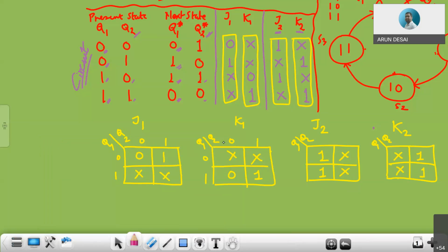So in this case, 1 is there, so we can group like this, right? So J1 basically is, this is what: Q1 is converted from 0 to 1, so Q1 cancelled. Q2, Q2 with 1 is Q2, right? And not complement, right? So this is basically Q2.